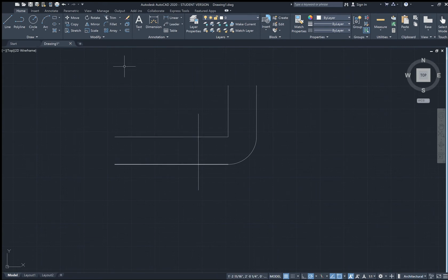these 2 lines here, we're able to click the trim command, and basically we're gonna select the region that we want our line to exist in. So let's say we wanted to eliminate these 2 corners. All we do is we choose to keep these 2 lines here, click enter, and by selecting object to trim, we can select this one. And what this does is, it eliminates this line on the inside here and keeps this one on the outside.